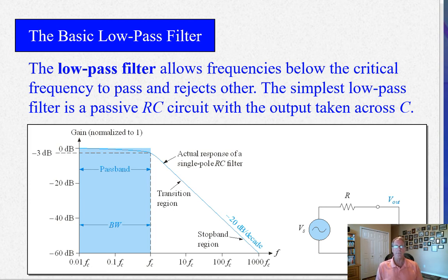It's not something that is not ever used. It's used all the time, very common. However, it's got some drawbacks. What are the drawbacks? Well, you've got this resistor in series with the source feeding the output, right? Well, normally what you want is a very low output impedance from your circuit.